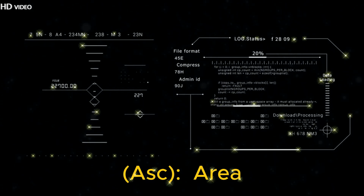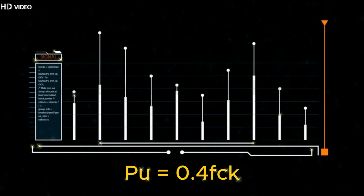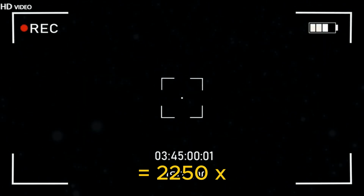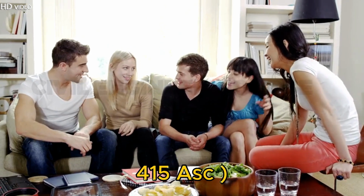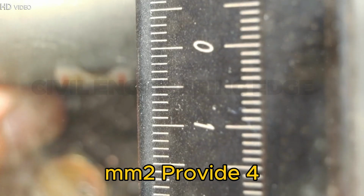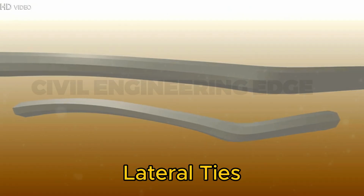3. Calculate required steel area Asc. Area of concrete Ac equals 250,000 mm2 minus Asc. Pu equals 0.40 fck Ac plus 0.67 fy Asc, so 2,250 by 10^3 equals 0.40 by 20 by (250,000 minus Asc) plus 0.67 x 415 Asc. Asc equals 925.75 square millimeters. Lateral ties design.